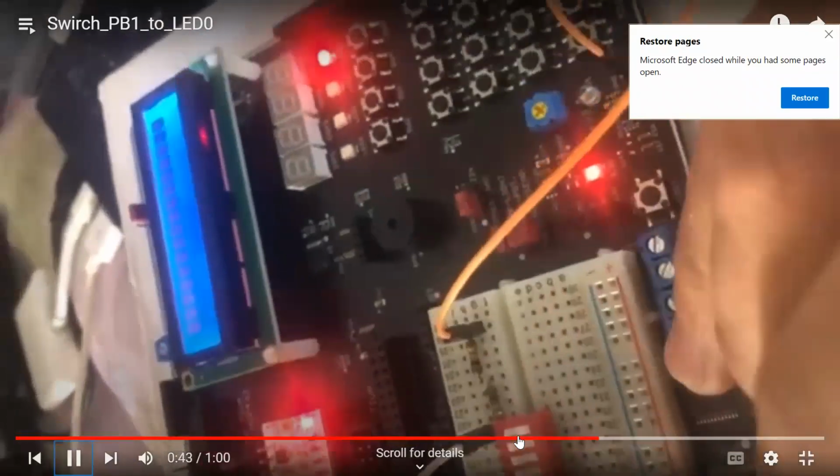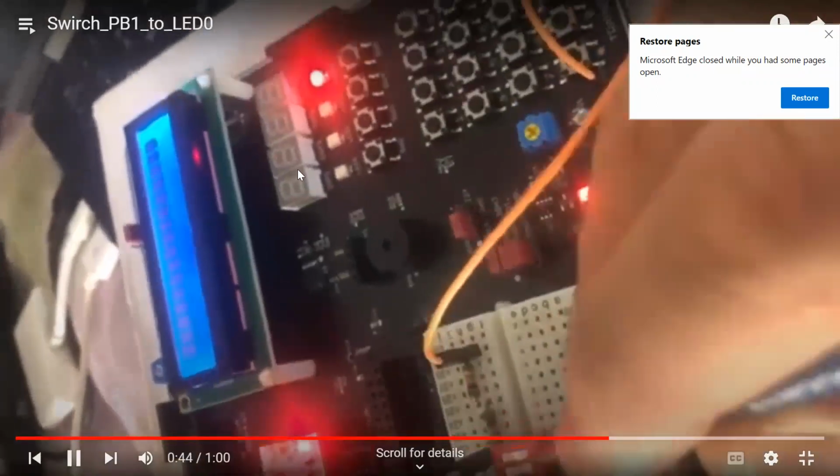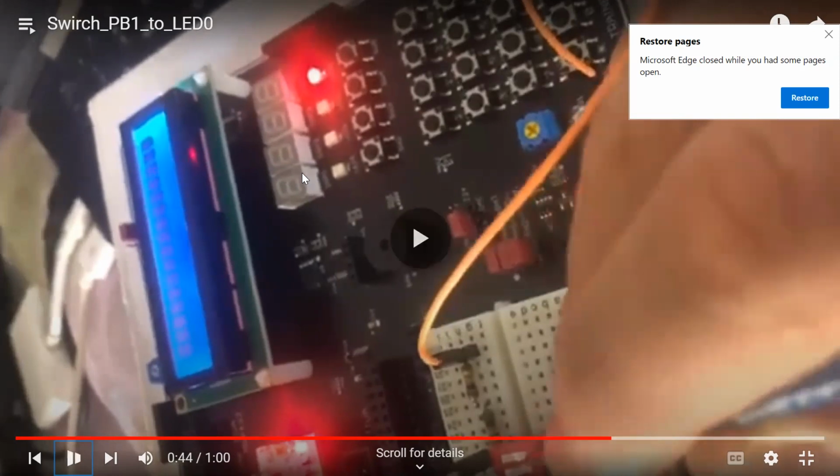So once I turn it on, this switch is gonna put here 5 volt. The program is gonna read the 5 volt and turn the LED on, as you see here. And it's gonna continue on. Big difference between this one and the push button. In the push button, when I press on, once I release, it's off. That's how a push button works. But here, it's gonna continue on.